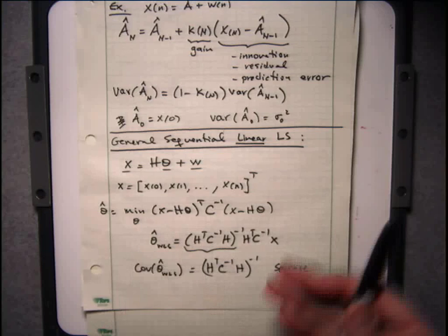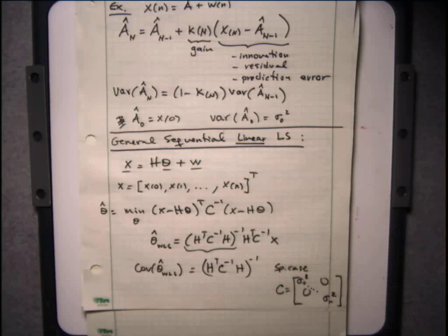But still, you can compute an estimate, compute the covariance for the estimate, and then try to see if you can write that estimate in terms of the previous one. It turns out you can in most instances, and if you can't, then you linearize to write something like this. What you end up carrying forward from iteration to iteration is both the estimate and the probability density for the estimate. Here we simply carried forward the estimate and the covariance of the estimate, because that was all we cared about.